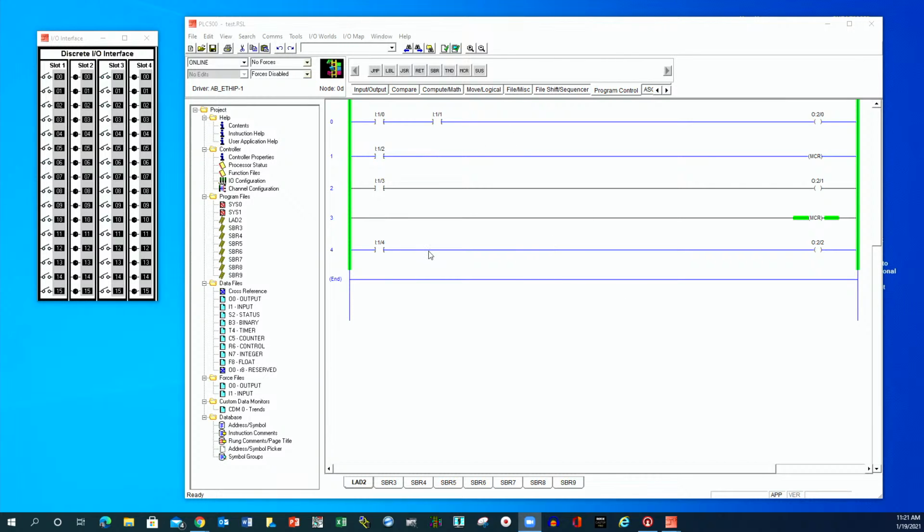So basically what's going to happen is you're going to have your MCR fence here. This one here is going to be positive or true, and because there's no conditions, it's on. But the zone is not activated because the beginning one is not. But if I go to input 1, 2, I click on it, now this zone is activated. That kind of makes sense. When the start is activated, you're going to see the whole thing activate. You could put input 1, 2 down here if you wanted. It really doesn't make a difference.